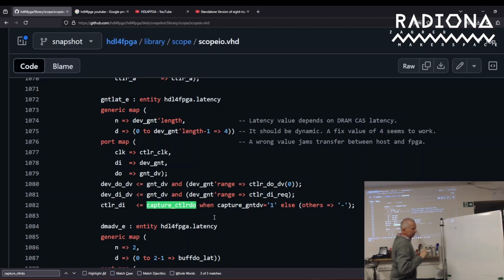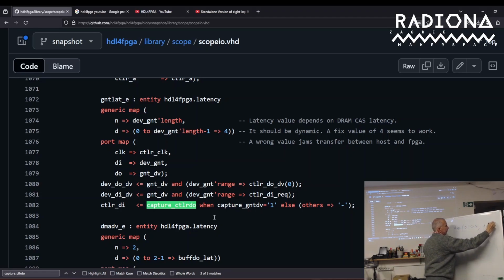the names of the generics are not the best. When I was coding, this is what I chose. T0 has a latency of 4, T1 has a latency of 5. You can set it to 0 and it will be a wire.